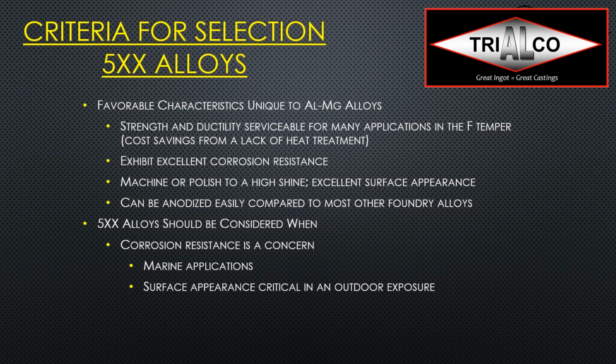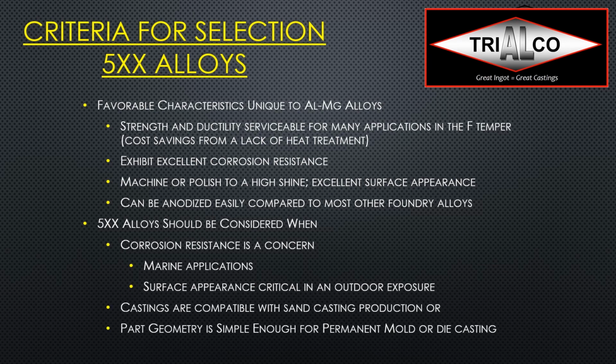We see nowadays more and more parts that get special anodized, antimicrobial anodizing and things like that. They are ideally compatible with sand casting, or if the part geometry again is simple enough, then you can do permanent mold, or in some cases even die casting.